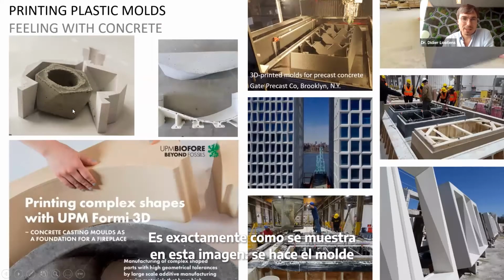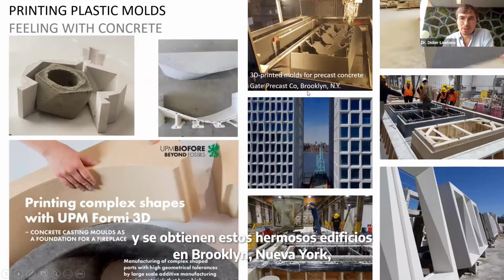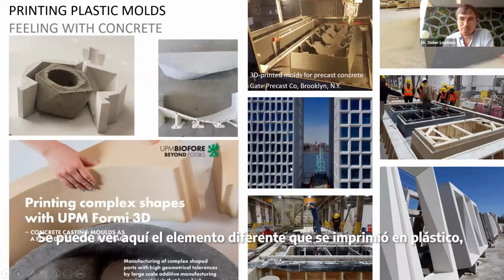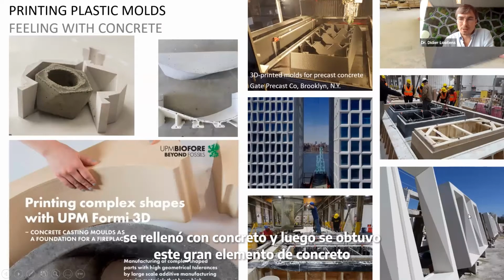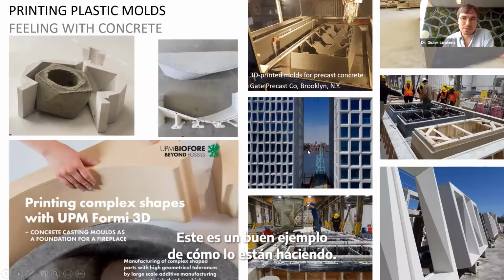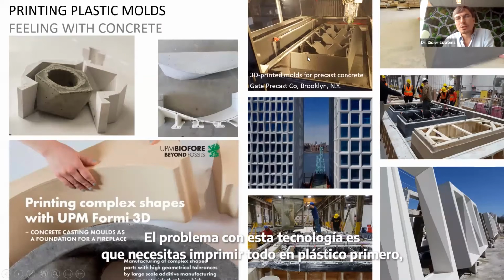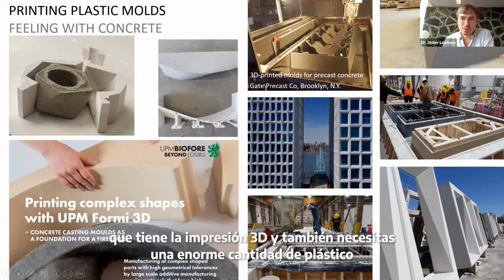It's exactly like what is shown in this picture. You make a mold, and you can pour concrete with different kinds of design. And you have these beautiful buildings in Brooklyn, New York City, that were made with this design. You can see here the different elements that were printed in plastic, poured with concrete, and then you have this large element of concrete that was installed in this facade. That's a nice example of how they are doing that. The issue with this technology is that you need to print everything in plastic first. You can reuse this mold, but if you reuse it, you don't have the diversity of design that 3D printing brings.